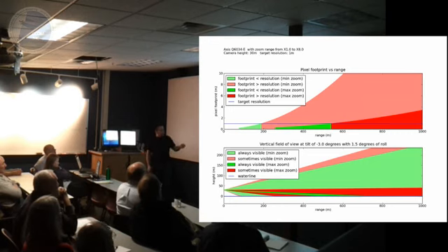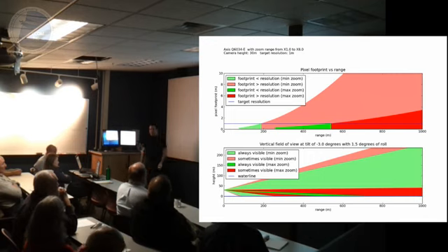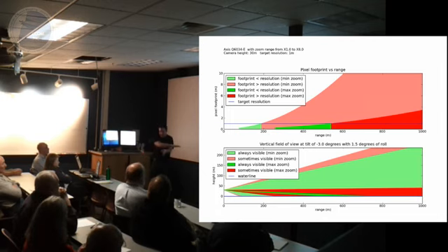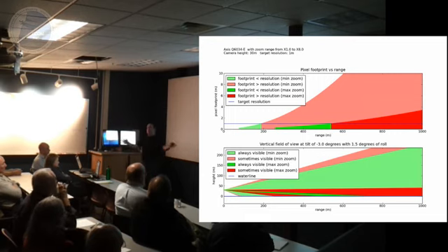Now, by zooming in 8 times, everything comes closer. We don't get to a 1 meter footprint until we get way out to 500 meters. And at a kilometer, we're still at about a 4 meter footprint. So having a narrow field of view is what we have to do. But if you have a narrow field of view and you want the same coverage, it means you have to take a lot more pictures to cover what a wide field of view can do in one. So those are the drawbacks.